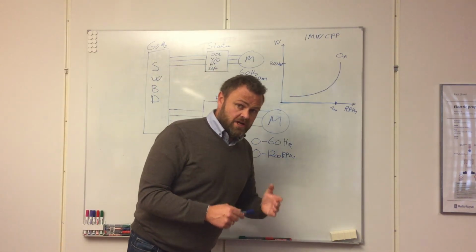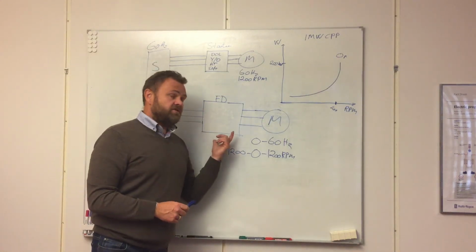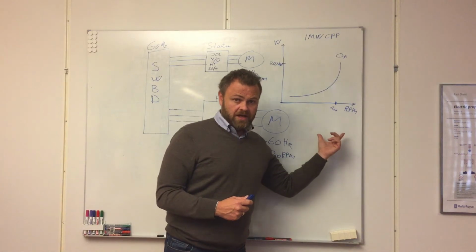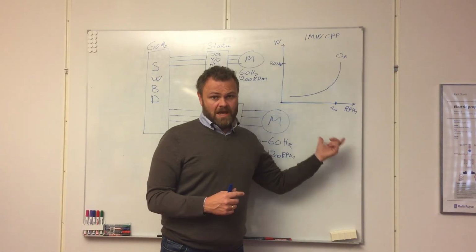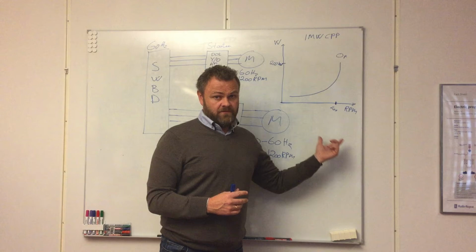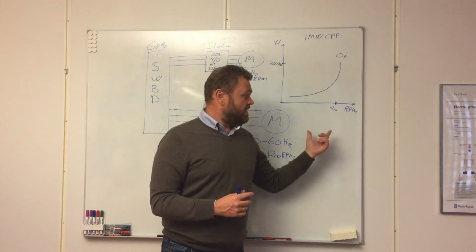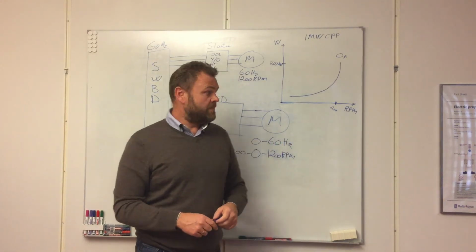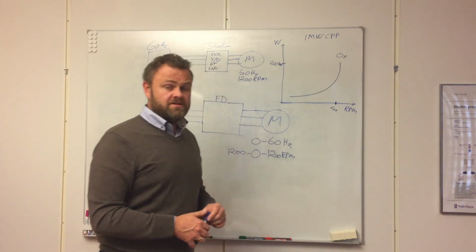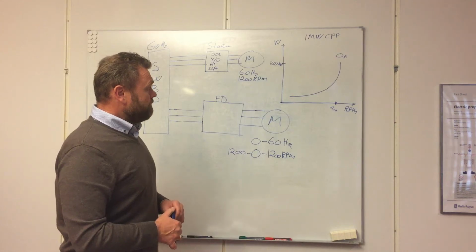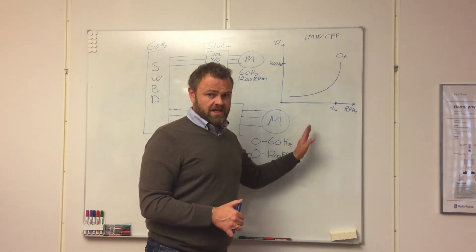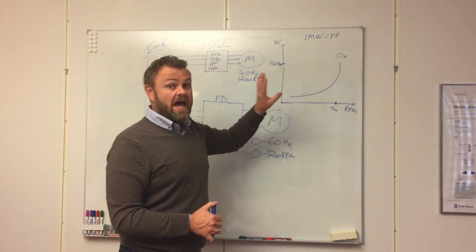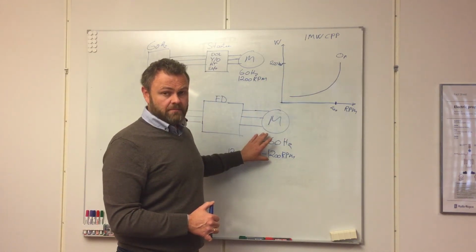And of course, when you have the frequency drive, you can as well look into the propeller and see if maybe you can pick a fixed pitch propeller to save the controllable pitch equipment. However, the optimum, really best solution is to have controllable pitch and controllable RPM.